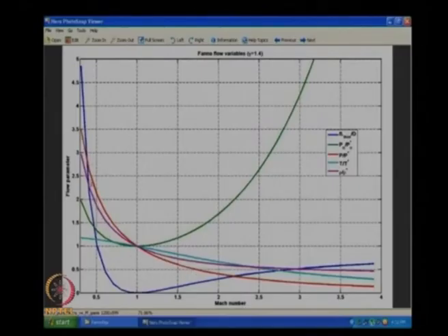Of course you have to again remember that the flow is going to go only up to M equal to 1. Okay. It is not going to keep on decreasing as I increase Mach number, that is wrong. If I am in subsonic, I find that the pressure decreases. If I am supersonic, the pressure increases. Is this logical? Yes, it is, because my Mach number is going to go towards M equal to 1 in both directions, and if it is subsonic, it is going to accelerate, which means my pressure and temperature should decrease.